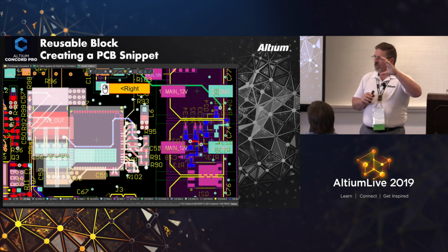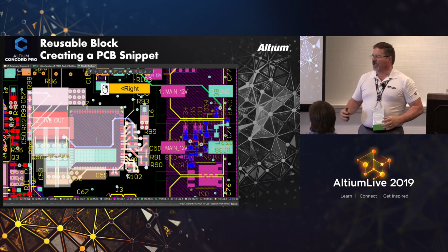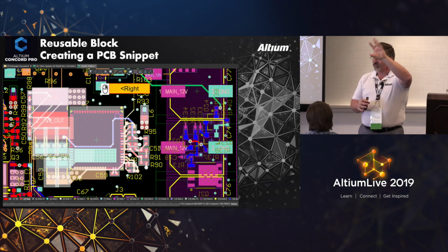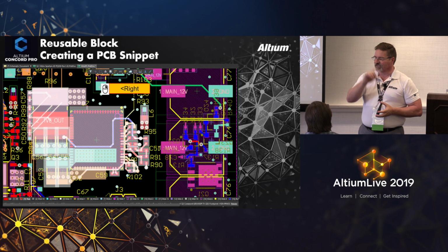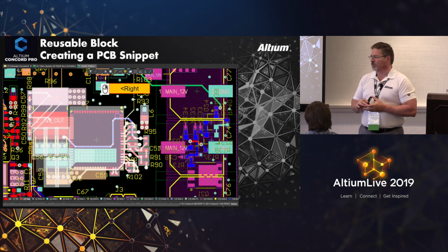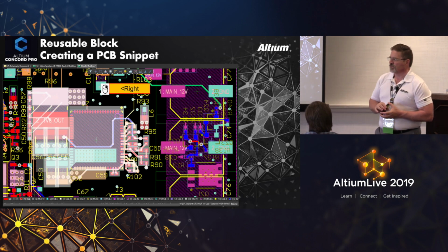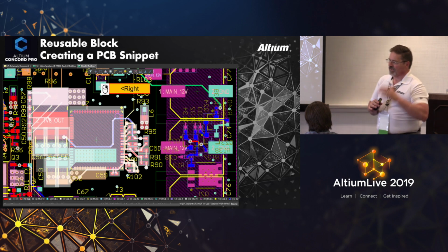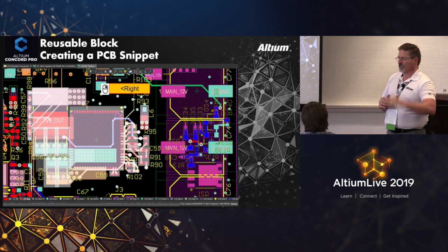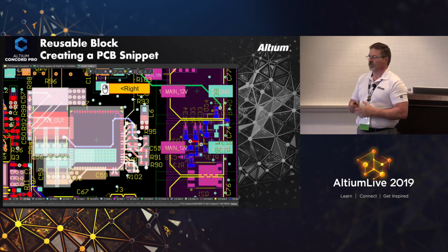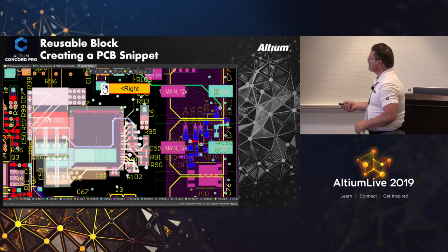If you have a reusable block, let's say it's a channel or a driver circuit of some kind, but it's 8 channels, for example, in an audio circuit. You simply lay that down. You don't have to lay it down 8 times. There's a syntax when you give it a designator, it actually will copy it and repeat it 8 times. So there's a technique for that to not have to copy it each time. And then each channel will be re-annotated according to what channel they're in. So multi-channel designing is really cool in Altium. They made it pretty easy.